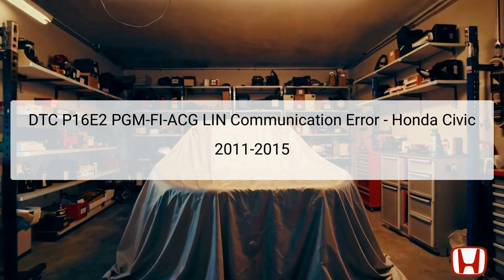The components involved include the battery sensor, which monitors battery voltage and conditions, and the ECM, which controls various aspects of the engine performance. These components can be found in the engine bay. The battery sensor is typically near the battery, while the ECM is usually located under the dashboard or in the engine compartment depending on the specific model. Proper communication per the LIN circuit is essential for efficient power management and to avoid potential engine performance issues.